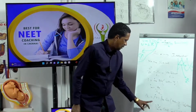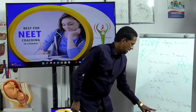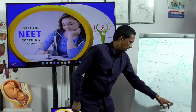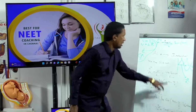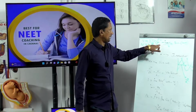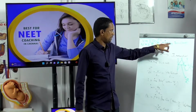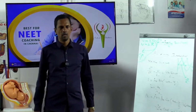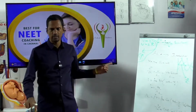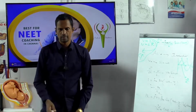So what will I get now? Im Vm, and sin omega t minus pi by 2 is minus cos omega t, times sin omega t. If I substitute this value, I will get minus Im Vm by 2 into sin 2 omega t. Okay, you understood this?